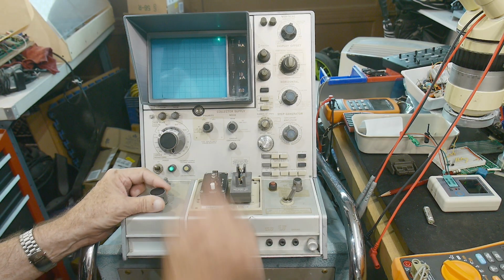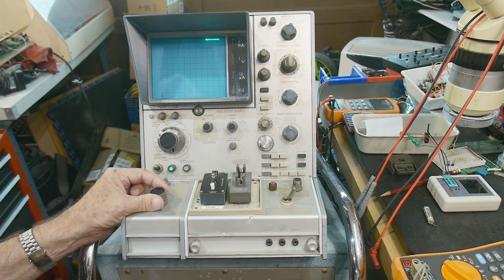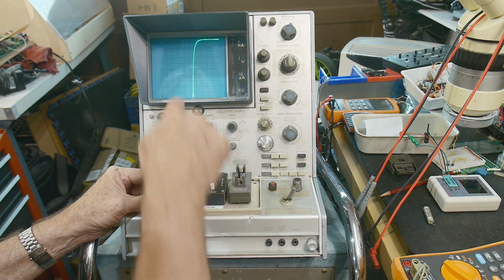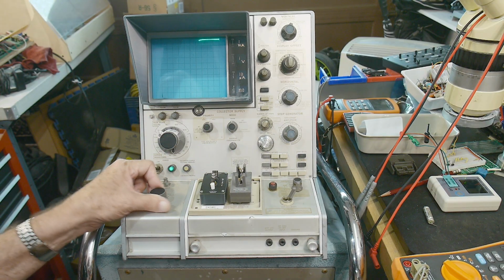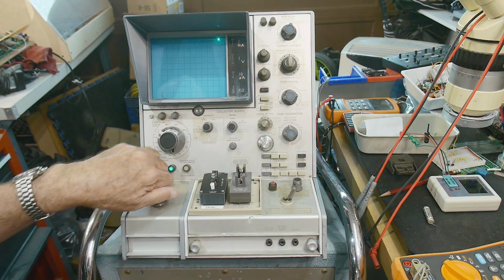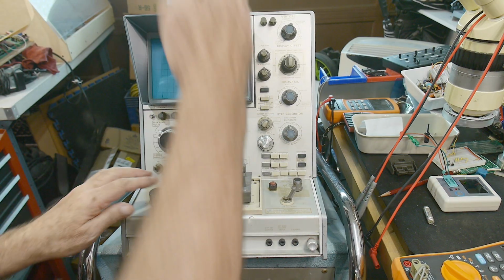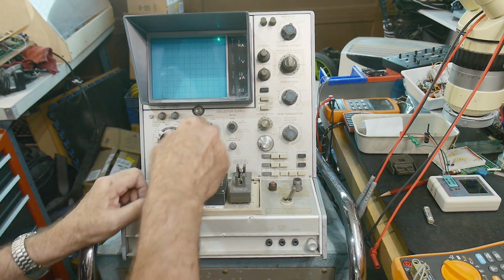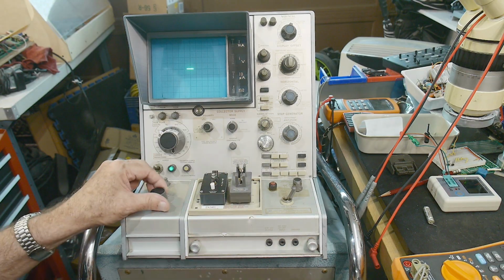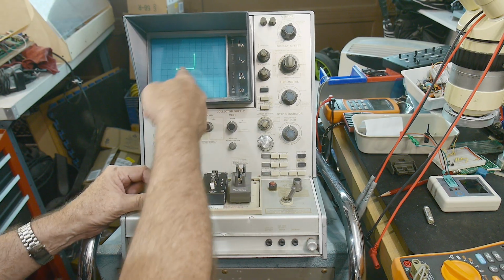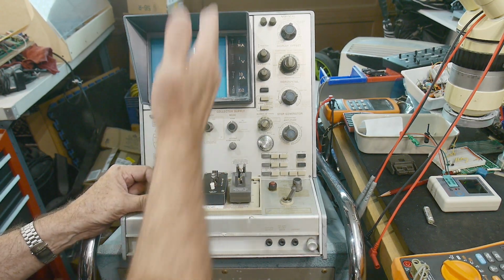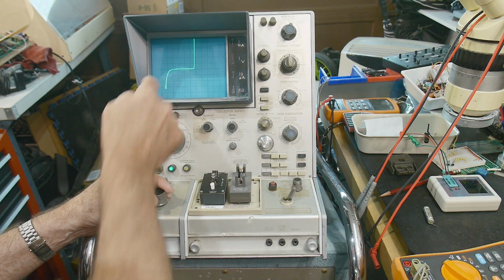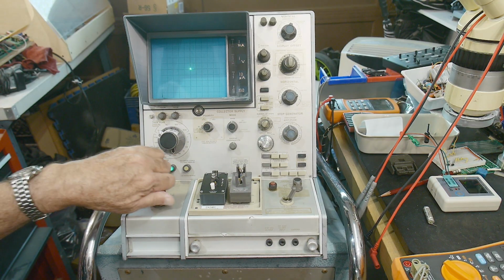So here's 1 volt per division. 1 volt, 2 volts, 3 volts, 4 volts. At 10 milliamps, it's about 4.7 volts. And this is a 4.7 volt Zener. And so that's a Zener. A lot of people like to see the forward part and the reverse part of Zeners. Well, there's a button on here to do that. You can press it here, and you can get the forward. So 0 is right in the center. It can go forward conduction and reverse conduction. So that's a Zener diode, right?